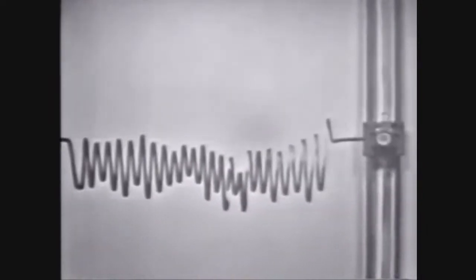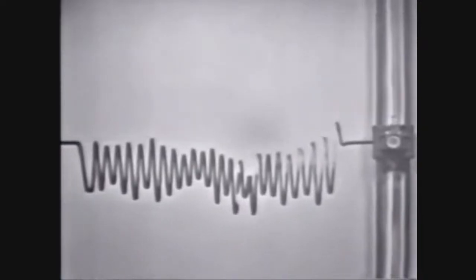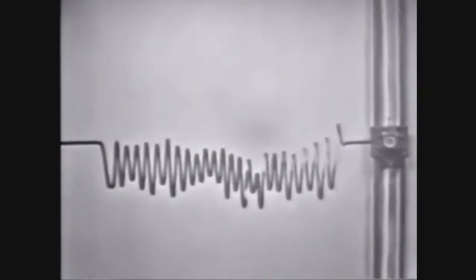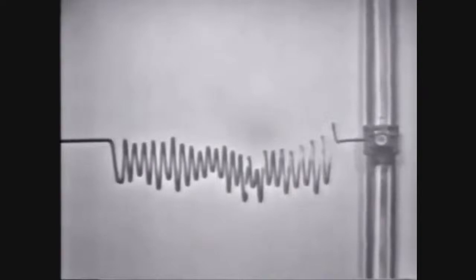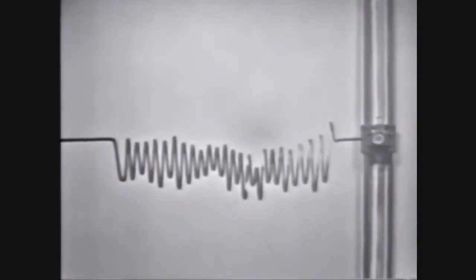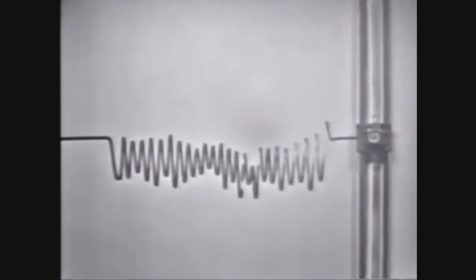and if we could add it in the proper amount, we would have a waveform of constant amplitude and constant frequency. Now, our graph shows us that this method produces a waveform of almost continuous amplitude and stable frequency. This is essentially the wave shape we want out of the LC oscillator. Constant amplitude and constant frequency. Of course, this graph does not show that by any means, but it does illustrate the point.